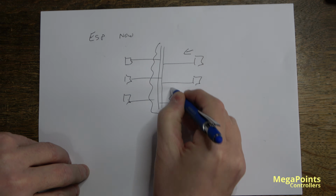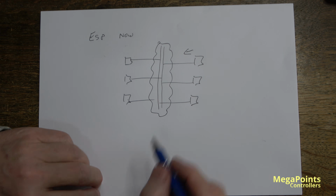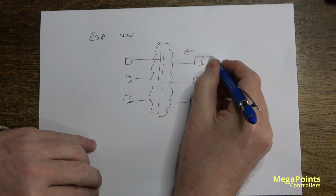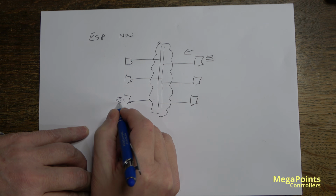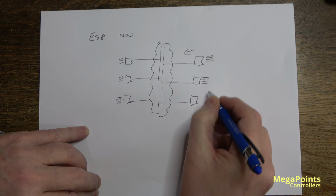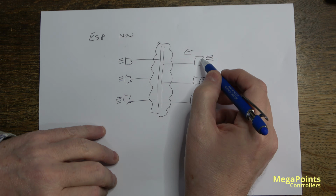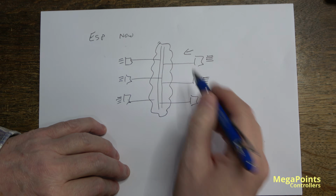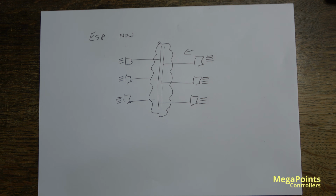What ESP Now does is on the Wi-Fi, it uses ESP's protocol, and it tries to hide the physical wiring. So we're using Wi-Fi now, and each board maintains a list of each other board, and so every single board on the network has this list of boards that it should communicate with. There might be something else on your network and it should not communicate with that. So when this board sends a packet, it doesn't actually know who it's intended for, it just knows it has to send it.